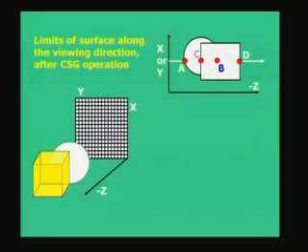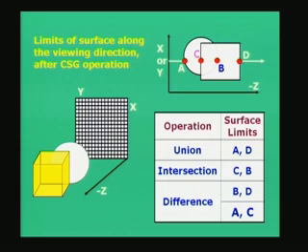and it intersects also the solid cube at 2 points C and D. So, as I said before, part of the sphere was inside the cube or vice versa, and when we create a complex structure out of these two primitives, either by union, intersection or difference, this is what will result. That means this table tells you what the surface limits are after the regularized Boolean set operations on these two objects, and where the ray intersects that final structure. If you look at the union of these two structures, the sphere and the cube, the ray will intersect at the two limiting bounds A and D.